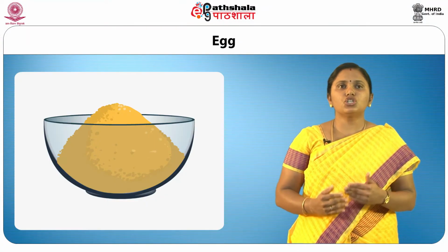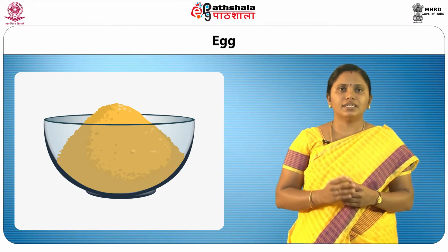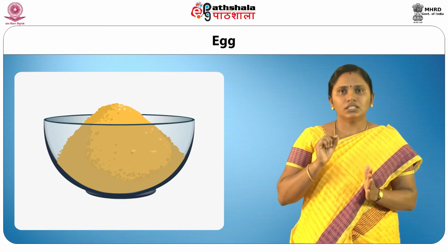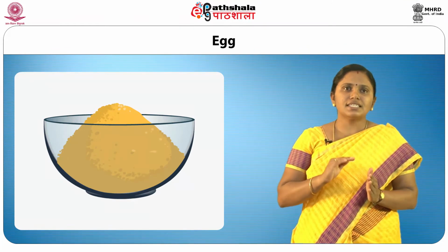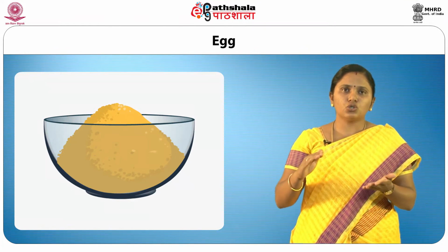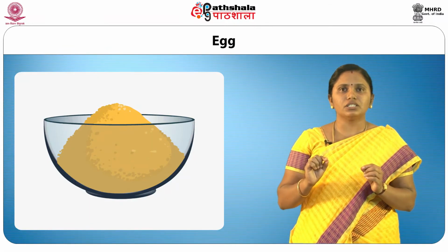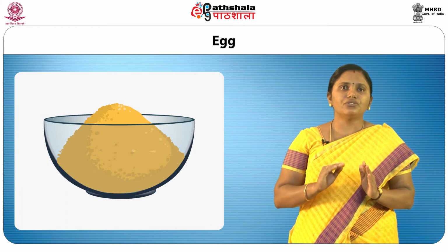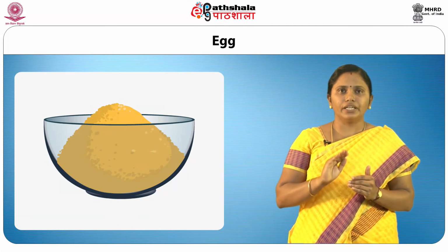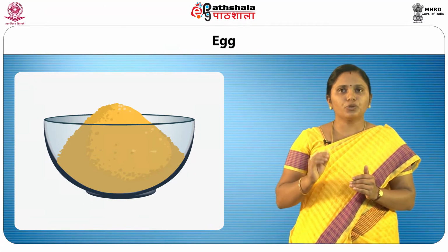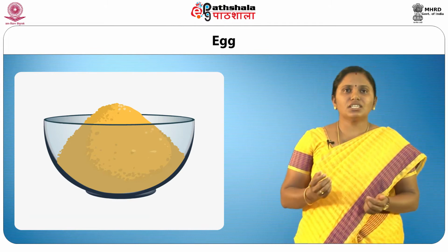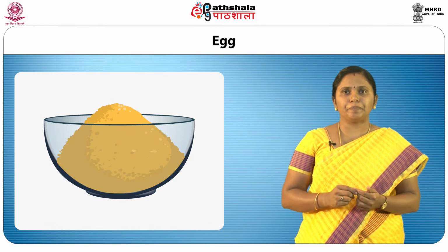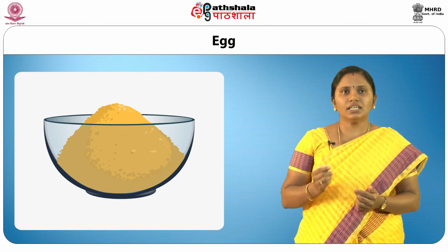Now, look into egg products. Liquid egg is mixed with stabilizers to a thick cream. The mix is then filled into trays to a depth of 10 mm and the product temperature reduced to -25 degrees Celsius. When this temperature is reached, cooling is stopped. Evacuation continues to less than 0.07 kilopascal. Then the plates are heated.